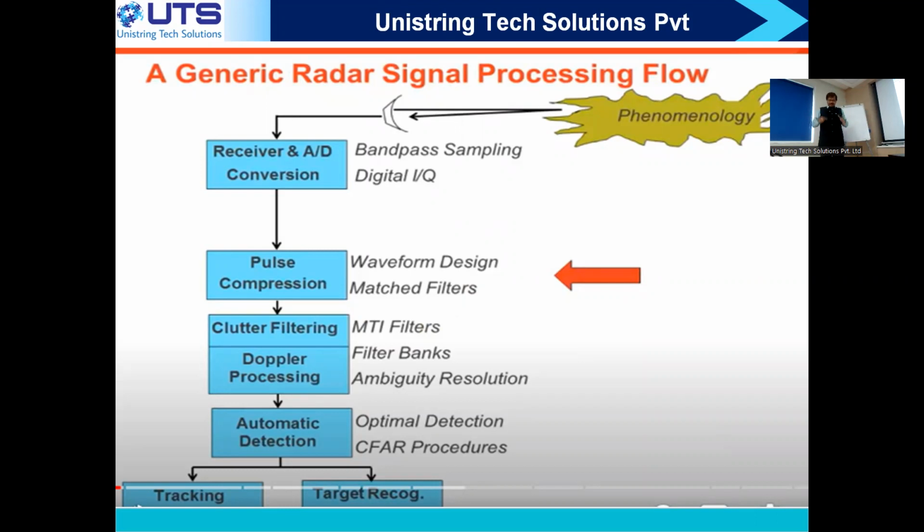Let's say in rotating radar, I have now detected. I'll go one complete rotation and come back. Now again, because it's 10 meter per second, if my rotation is 1 second, it would have moved 10 meter. Now I will get a range of 990 meters. 1000 minus 10, 990. Another 1 second, it will come 980 meters. All these in my algorithm, I'll be connecting these dots and will be able to show in a map with a line, hey, there is something coming like this. This is called a track.